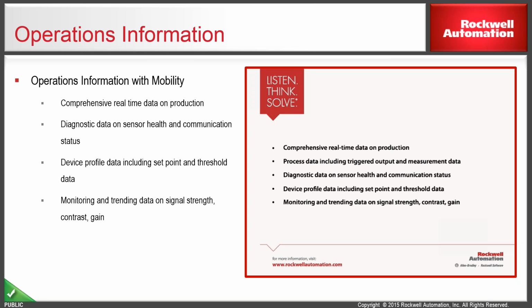Whenever there is a degradation in the performance of a sensor, there is an indication on that mobility device as to which sensor is the challenge. It points out the position of that sensor, and then the operator can go there and quickly do the maintenance. Once the sensor returns to the healthy condition, the status changes on the HMI.